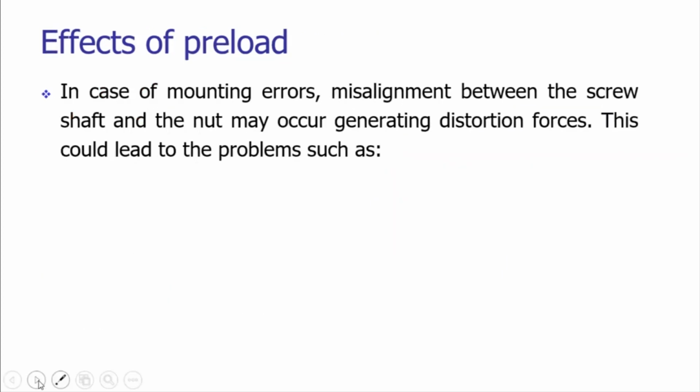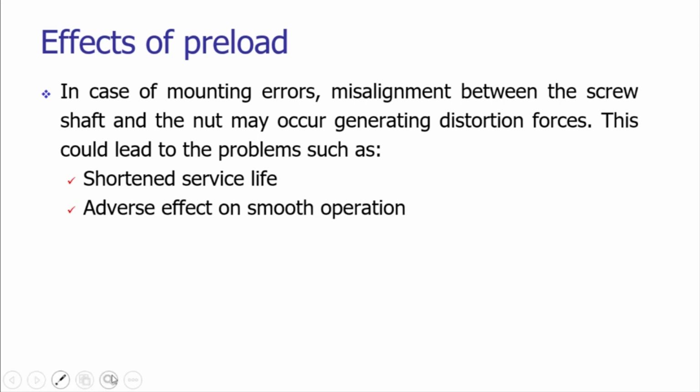But there may be chances of having mounting errors if the spacer is not properly mounted, and if the tension that is applied on the nuts is not proper, due to the misalignment, there are chances of having distortion forces. Due to these distortion forces, the screw and nut arrangement may have shortened service life.